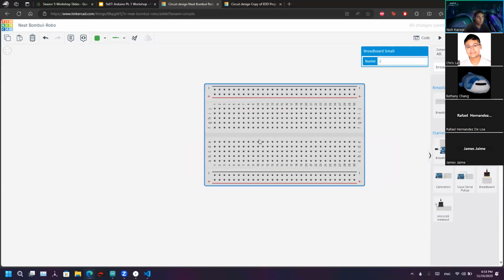Do we all know how the breadboard works and how connections occur in a breadboard? Okay. Just in case for those who don't know or are reviewing this later on: these 5 right here are as one bus, so you can connect 5 components to the same bus line, same circuit. There's a few of them going across the entire thing. You also have the main power bus line, being the negative here and the positive. So you can put different pins of components across different rows.